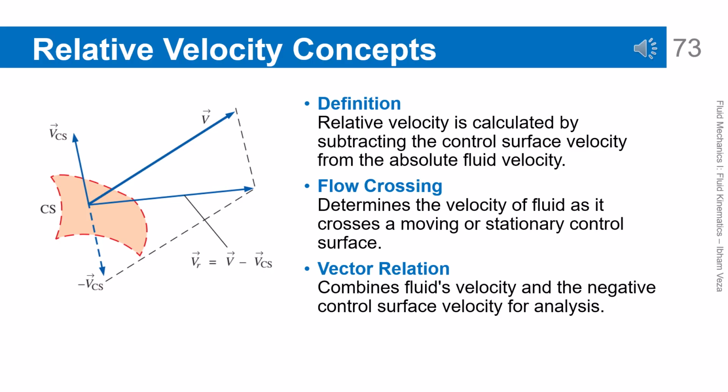This concept is important when the control volume is moving or deforming. The relative velocity determines how fast the fluid actually crosses the control surface. With this approach, flow analysis in moving systems becomes simpler. This concept is widely used in the analysis of turbines, pumps, and moving vehicles.